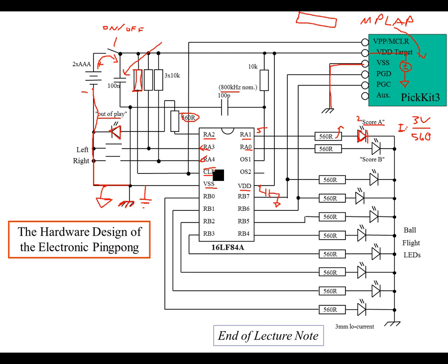So it has a slash over the top of it, which means it is active. The clear is active low. Now if you wanted to, with this pull-up resistor, you could put a switch here to ground, and then when you push the switch, it would reset your microprocessor. So that would be optional.